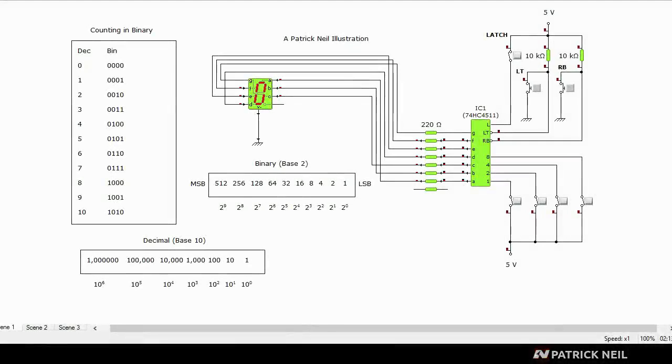In this video, I will explain how electronic circuits count. In order for my video to be interactive, I will include a decoder and a 7-segment LED display. The decoder used here accepts a sequence of voltage on its input, called the BCD code or binary coded decimal, and translates that into another sequence of voltage that will light up specific LED segments to form digits.